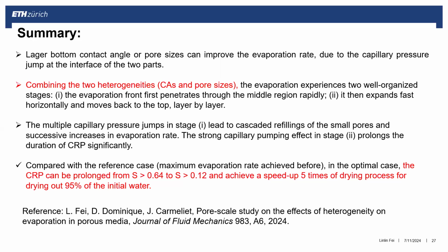And then we found that the evaporation experienced 2 well-organized stages. In the first stage, the evaporation front first penetrates in the middle. In the second stage, it expands fast horizontally and then moves backward. The multiple capillary pressure jump in the first stage will lead to cascaded refilling of the small pores and therefore successive increase in the evaporation rate. And the strong capillary pumping effect in the second stage will prolong the duration of CRP significantly.